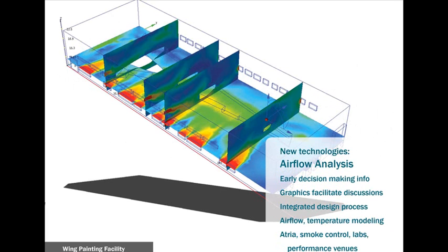Okay, so on the bottom of our presentation, our intro to this thing, I think we talked about new technologies in addition to working in existing buildings, and this is kind of like my harsh segue into that. We used to outsource our CFD, computational fluid dynamics modeling, which is just airflow analysis, where the air is going to go. We bought a package that sits on top of, it's a part of Revit, it's an add-in, and it exports it out to another Autodesk product that models airflow for us. We got pretty good at using it. We used it to model, like I said, where the air was going to go around the wing to make sure that the client was going to get a design that would meet their requirements for their robot painting things.